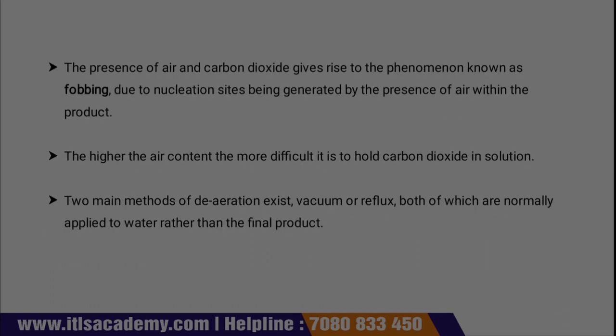The presence of air and carbon dioxide gives rise to the phenomenon known as fogging. This is again very important, due to nucleation sites being generated by the presence of air within the product. The higher the air content, the more difficult it is to hold carbon dioxide in solution. The second reason is that first the product deteriorates due to air, and second, the CO2 in any solution, if air is present, it is very difficult to hold the amount of CO2 in the solution.